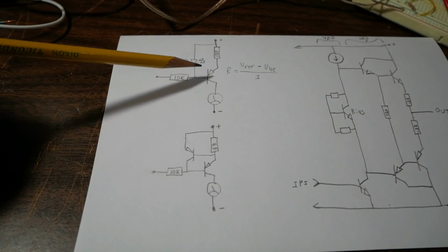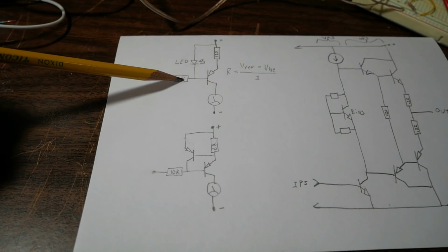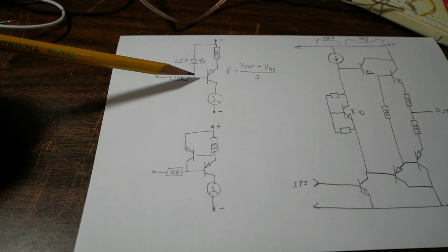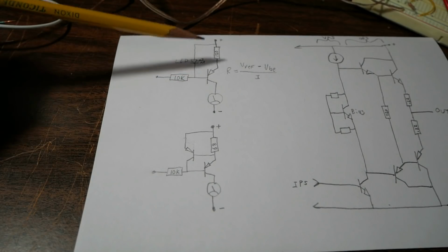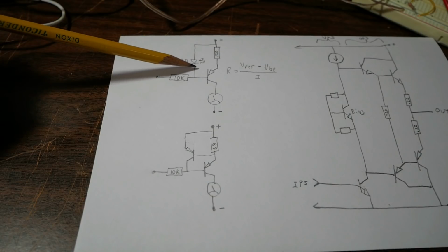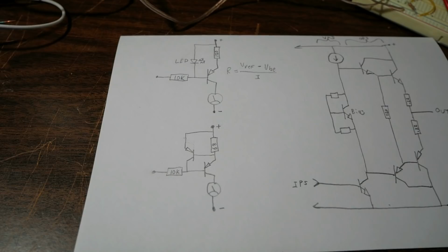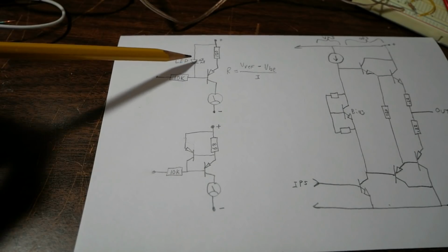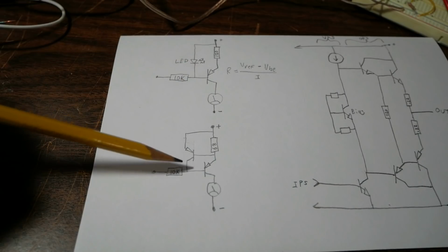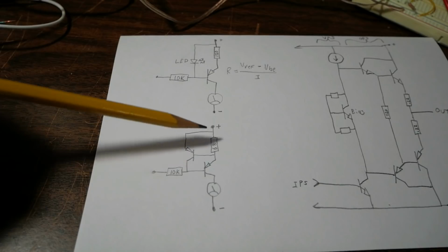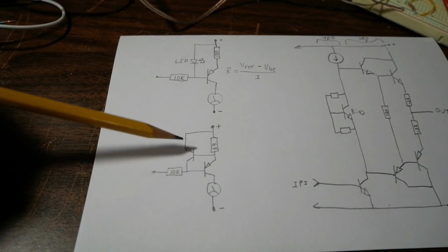So the basic layout of the circuit, you have a transistor, emitter resistor, a base resistor, because you want to limit the current. You're feeding some voltage into the base here to make the circuit function, and something that gives you a voltage reference. That could be a couple of diodes, Zener diode, very popular to use LED here. In this circuit, we replace that voltage reference with another transistor. The rest of it's set up just the same.